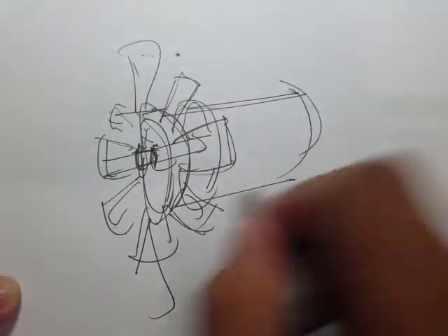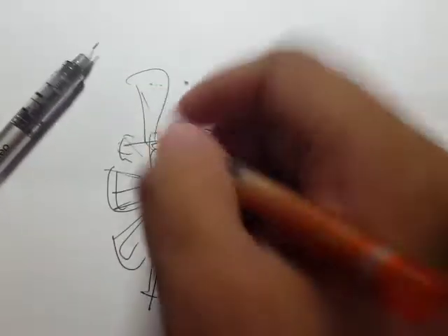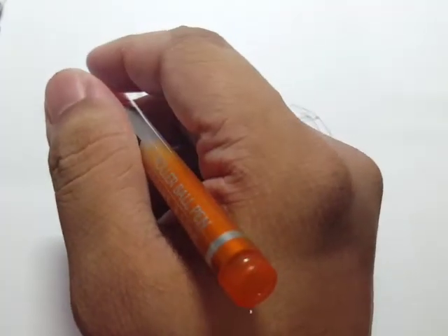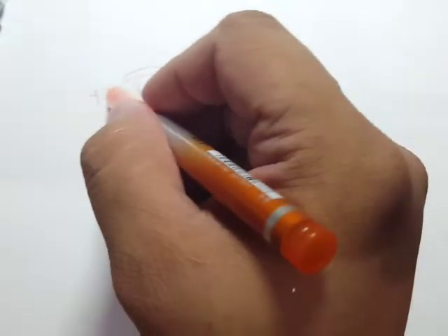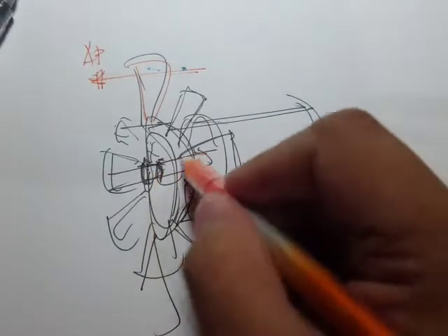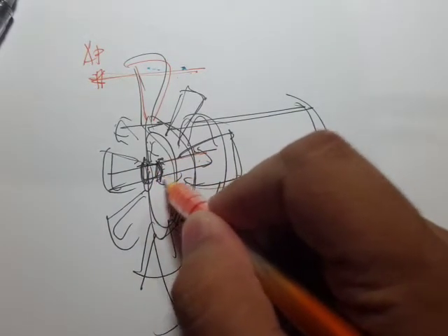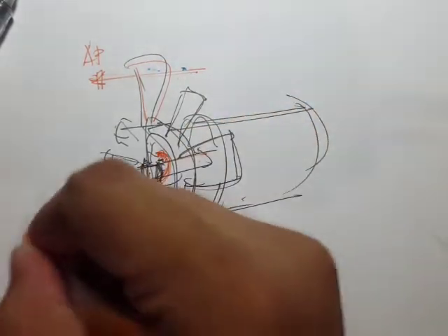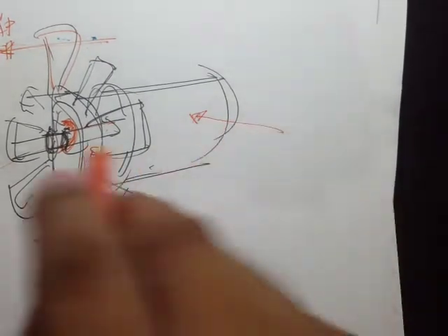And here's our electric motor. When we say air horsepower, that's the power delivered to the air, so that the air can move from one location to another or across a pressure difference. So that's the air power. But when we say brake horsepower, that refers to the horsepower delivered by this shaft right here. So that's the shaft. So there's going to be a brake horsepower, bhp. And when we say electric motor or power input, that refers to the input power to the electric motor.